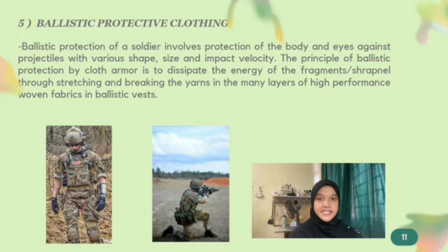Next, ballistic protective clothing. Ballistic protection of a soldier involves protection of the body and eyes against projectiles with various shapes, sizes, and impact velocity. The principle of ballistic protection by cloth armor is to dissipate the energy of the fragments or shrapnel through stretching and breaking the yarns in the many layers of high-performance woven fabric in ballistic vests.